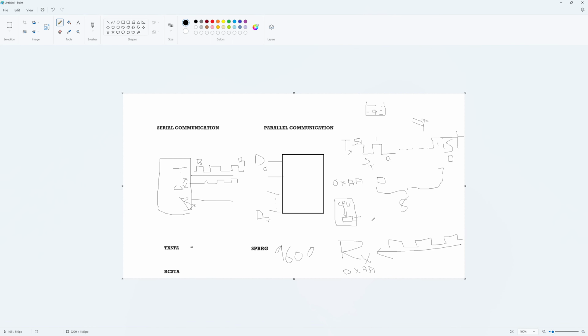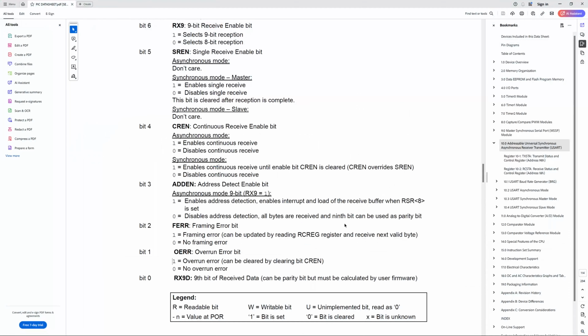Suppose data is coming into the microcontroller. After getting the data, the UART peripheral will tell the CPU, through interrupts or some other flags, that it received data. It is the duty of the CPU to receive that data and store it somewhere else, because we only have two buffers to store the data. If both buffers fill, that would be an error.